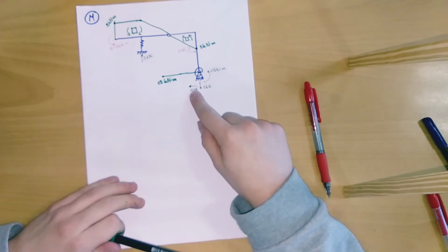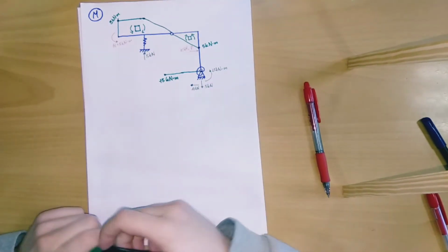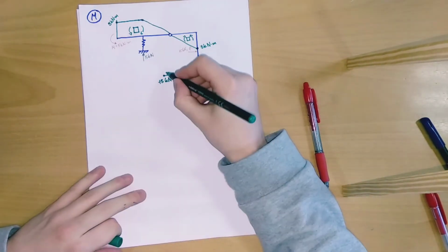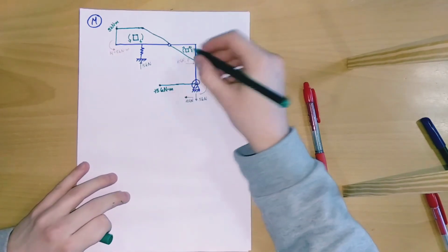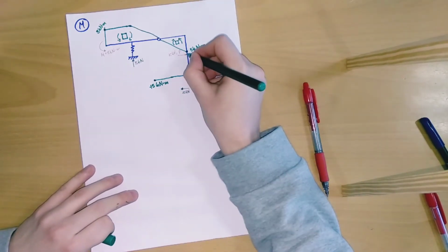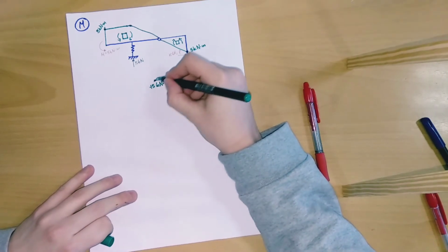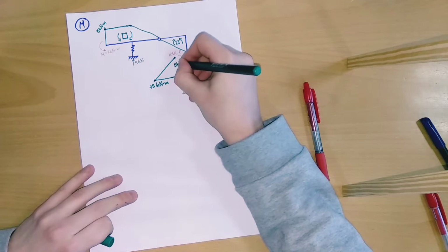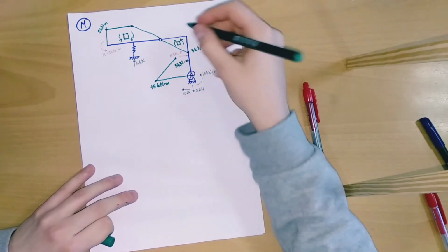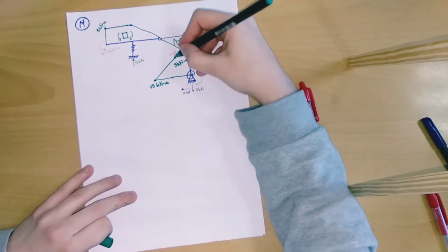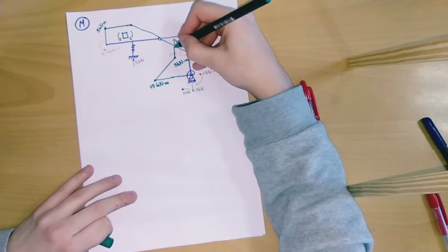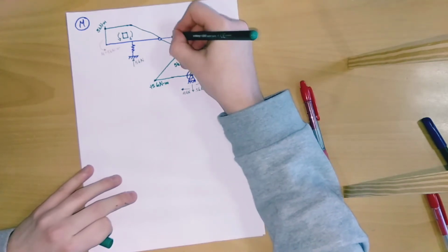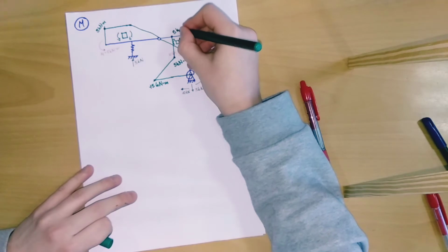This force is going to generate a negative slope, which is going to reduce the bending moment diagram to this point, to a value of 5 kilonewton meters. And then it's going to continue constant as there are no other forces in its path, till 5 kilonewton meters.